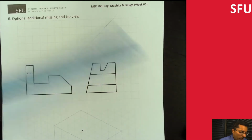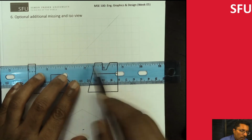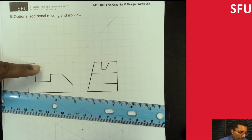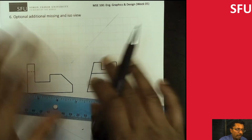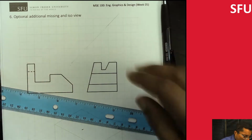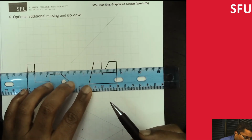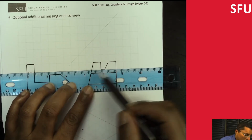I notice, if I use my ruler, or I can actually use grid lines, that these two are at the same height. That basically means this and this are probably one feature together. It looks like a flat line here and then two flat lines here. So that means I'm going to create some kind of planar object over here. Let's go a little bit further to identify the parts. This is actually aligned with the grid line, just a rendering error. It looks like this hidden line and these two are at the same height.